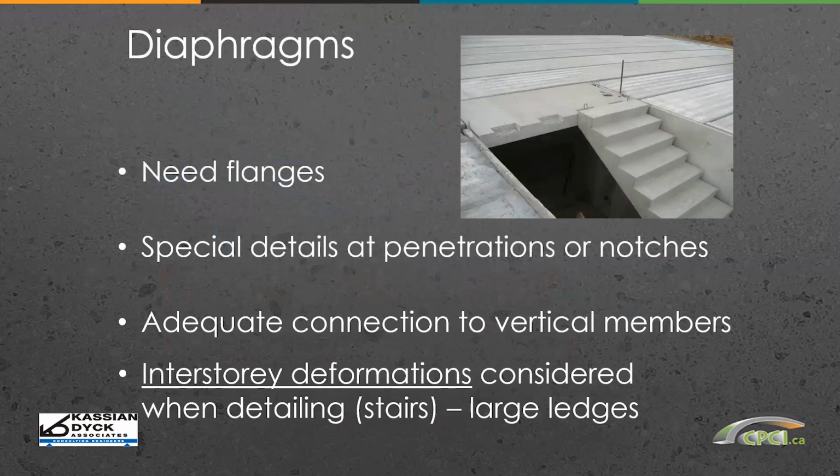But if you don't consider those interstory deformations during an earthquake, if the deformation is large, you could lose support at the end of a stairway, and you don't want to do that because occupants need the stairwells to get out of structures in an extreme event. So you do need to look at even your stair detailing and ledges to ensure that they have adequate capacity for going along with the seismic drift during an earthquake.